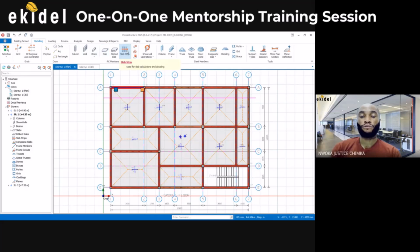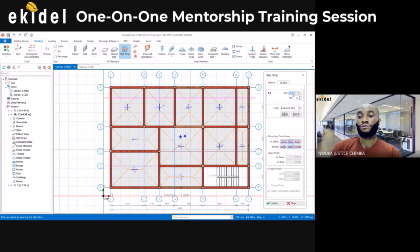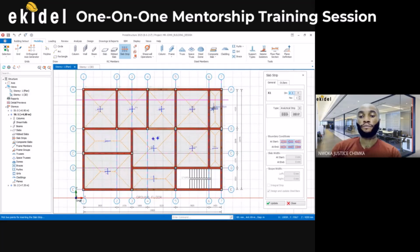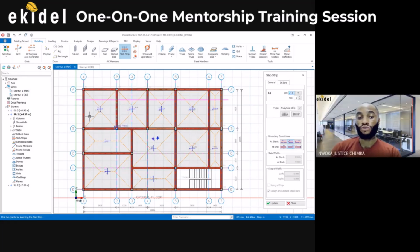Then slab strip here. Under slab strip, you can see that we have X direction and Y direction. The X direction is going this way, horizontally, and the Y direction is going in the vertical direction. So I'll begin with the X direction. Then I have to come here that says slab type. I'll make sure I am on this first one here, analytical strip. I'll click that first one.